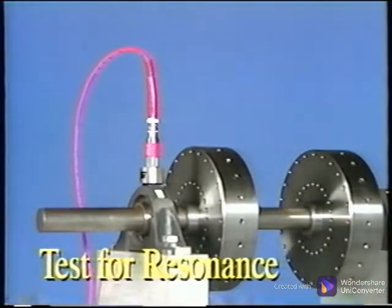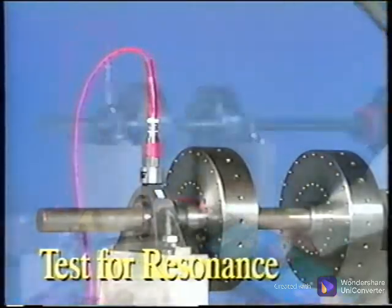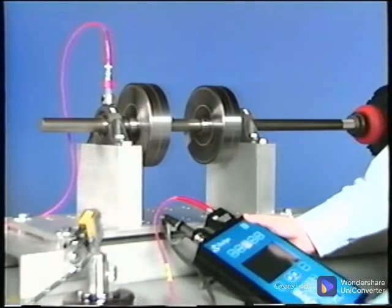Determine the resonant frequencies by performing tests for resonance, such as a bump test, or monitoring the peak and phase of the machine during a coast down. The running speed of the machine should not be within 15 to 20% of a resonant frequency.